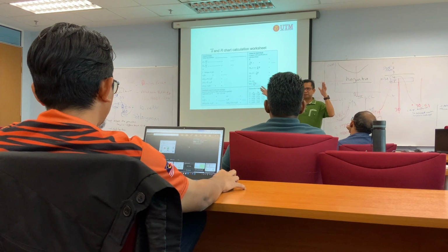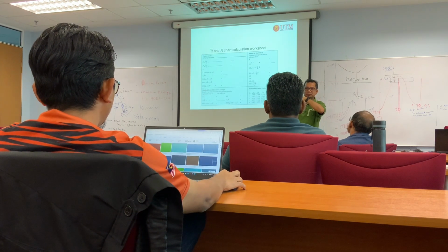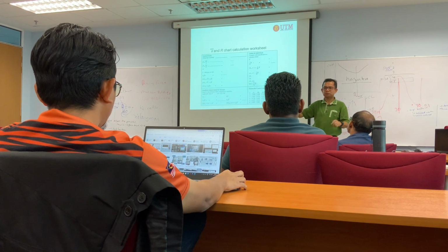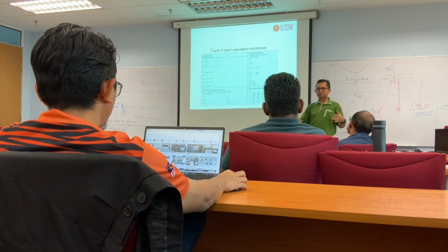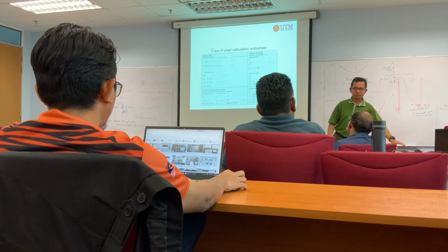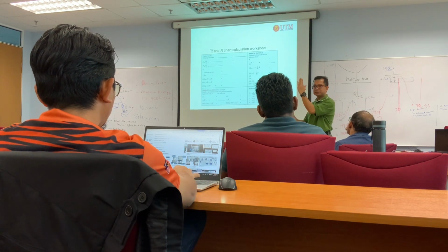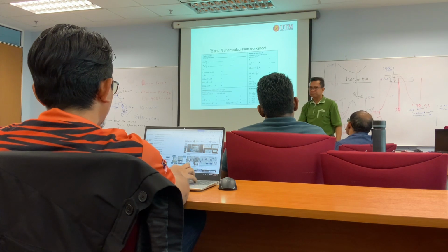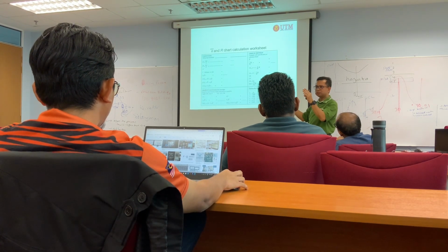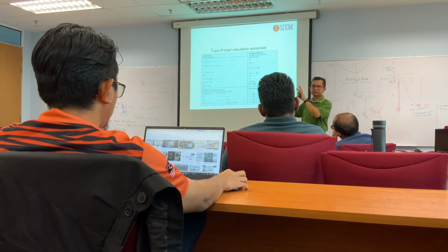What is the R bar? Because you want to see how much the deviation is. If the deviation is too much, then you have to check your tooling as well. Maybe you have a problem with your tooling, so it will affect your accuracy. Accurate is still accurate because it still lies on the mean, but if you have an accuracy problem, that will affect the distribution of your data.